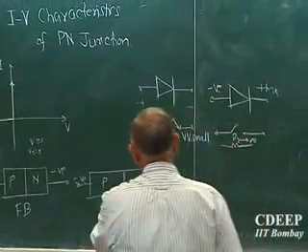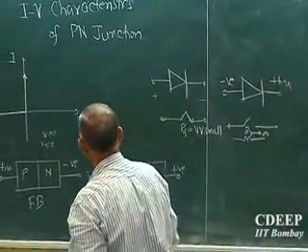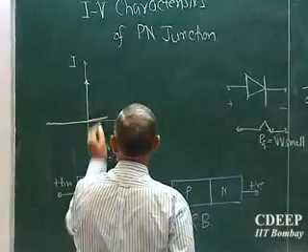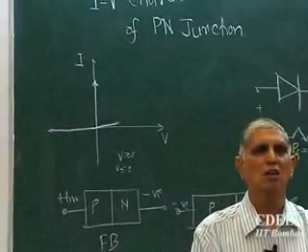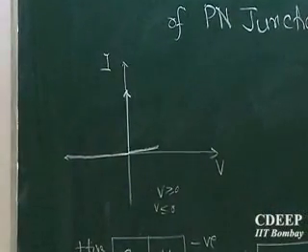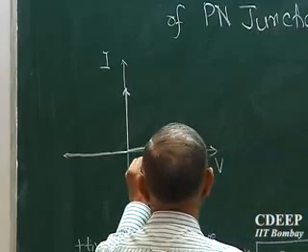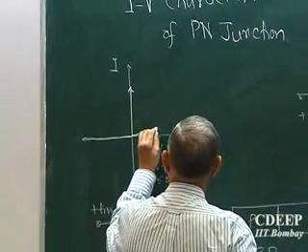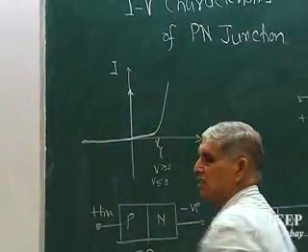However, when I actually try to use this diode or device, I figure out that initially there is a small current even if I apply forward bias, until a certain voltage, which we call cut-in voltage, the current still is very small and then starts rising exponentially.